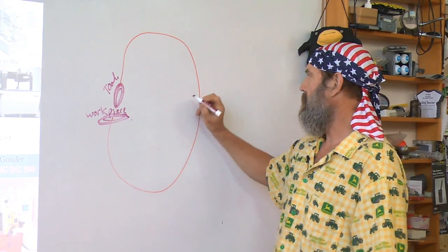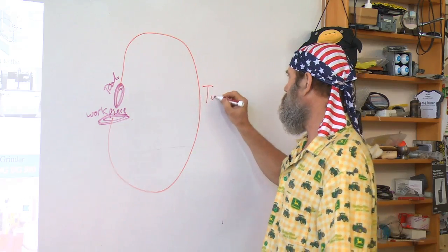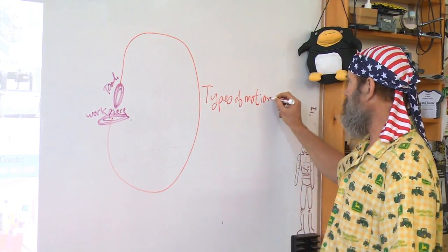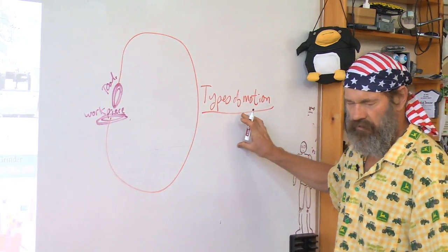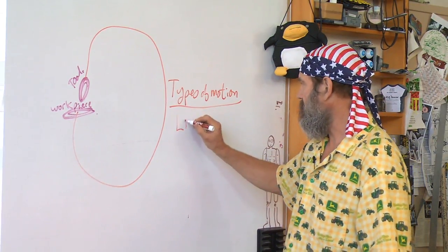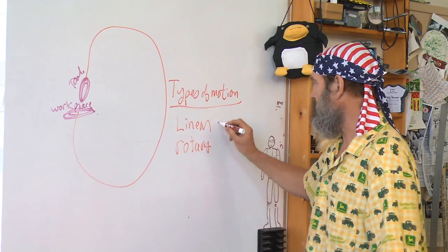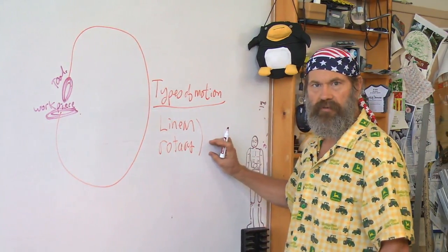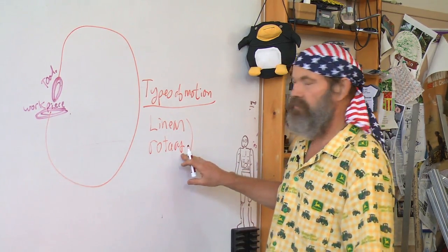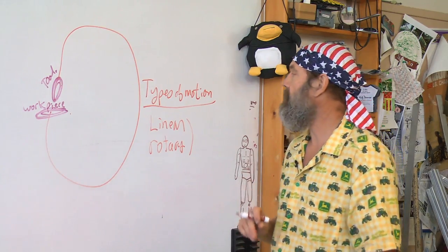What I like to do when I'm designing a machine is literally I have the tool, the workpiece, and I'll start writing down my requirements for the types of motion. And often this will come from your concepting of the machine itself in terms of, am I going to have linear or rotary motions, and what combination? I can have all linear or all rotary or some combination. Remember, from Topic 4, multiple rotary at the same point would give you spherical ultimately.